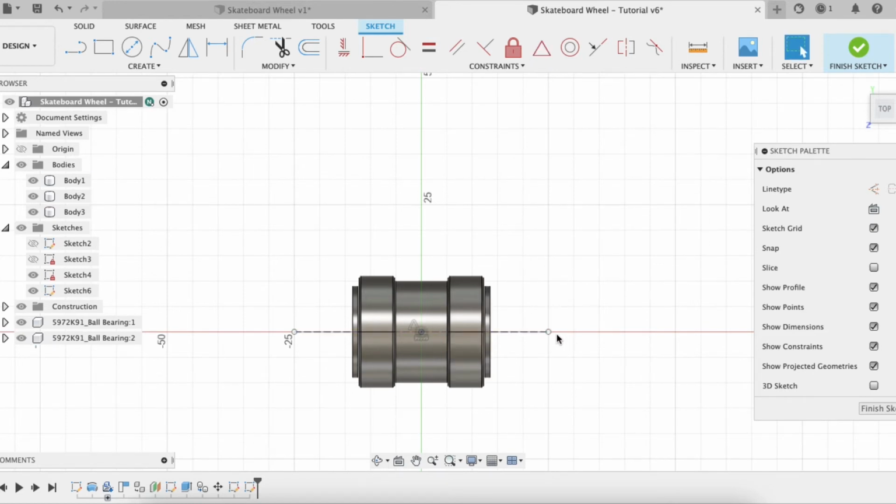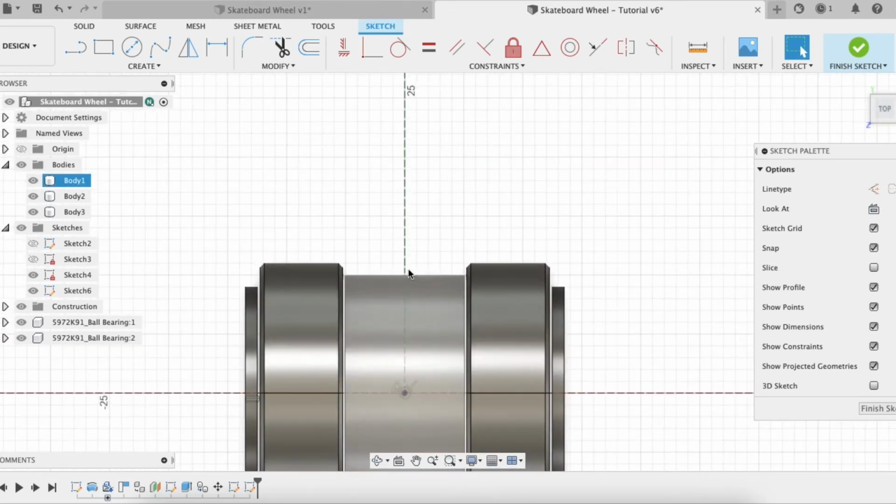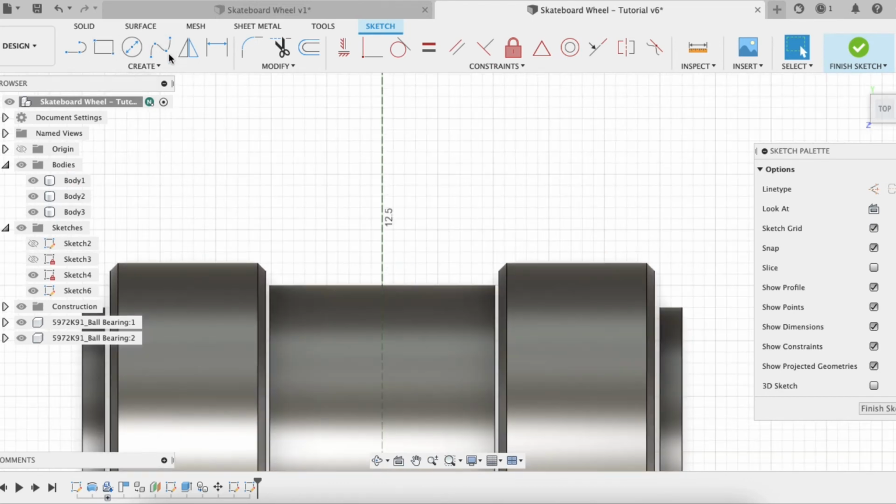we have our line connected to our origin, and we're going to draw a vertical line from our origin straight up. And this line will be perpendicular to the line we just drew. So I'm going to draw that in, change this line to a construction line, and pull it up nice and high because I know that the sketch we're going to be drawing is going to be 35 millimeters tall. So now that we have our construction lines in place, let's get started by drawing our first 2 lines.